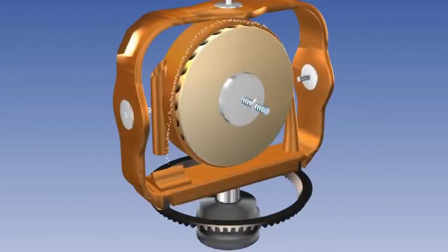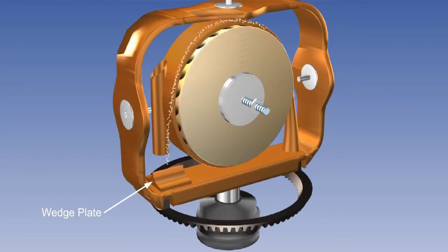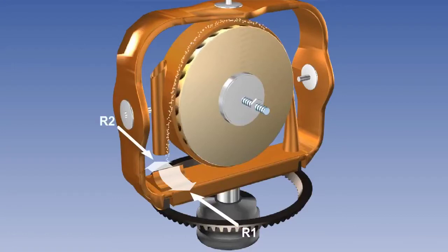The air jet provides coarse adjustment of the rotor spin axis. Fine adjustment is achieved by a secondary system which involves a wedge plate fixed to the outer gimbal. If we look closely, we can see that the airstream flowing around the rotor is directed at this wedge plate. The wedge plate normally separates the air jet into two equal pressure streams, producing equal reactions on the outer gimbal.